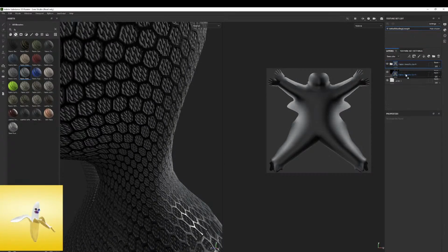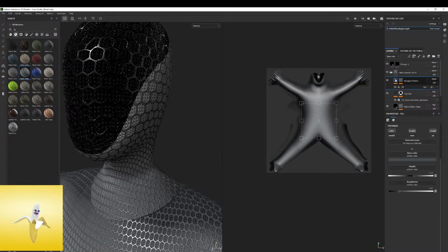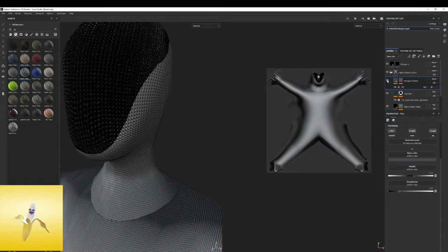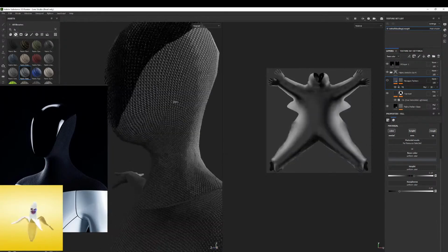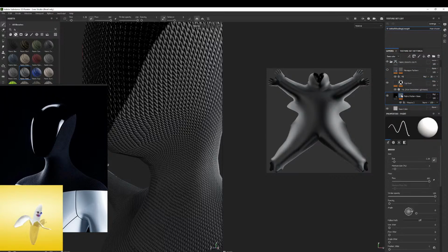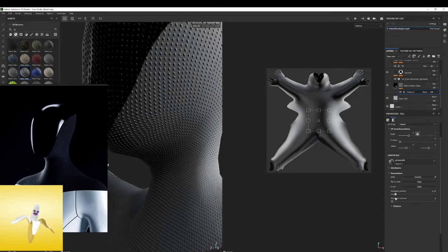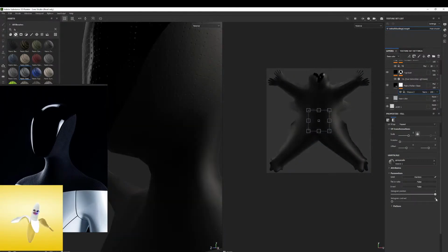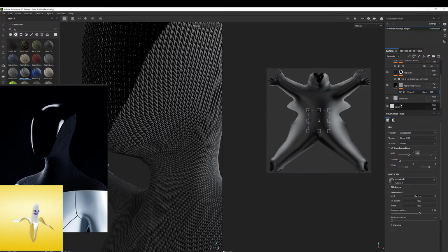And what I'm going to do is put it behind the glass. And then we're going to go to the settings, the hexagon pattern. I'm going to turn off that hexagon pattern because it doesn't have it on their thing. And then it already has a pretty good amount of stitching in there. I might lower the height map so it's not so strong, because right now the height map is coming off really strong and it's popping off too much. So I'm going to turn down the histogram position of our fabric.